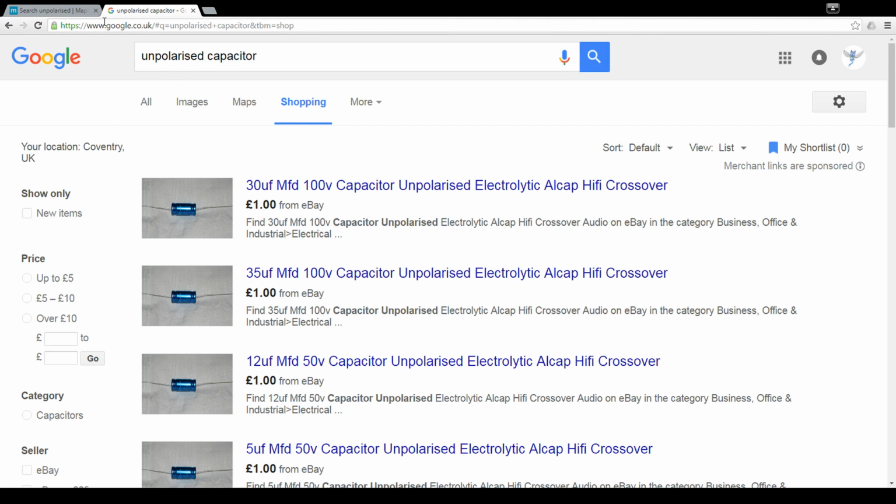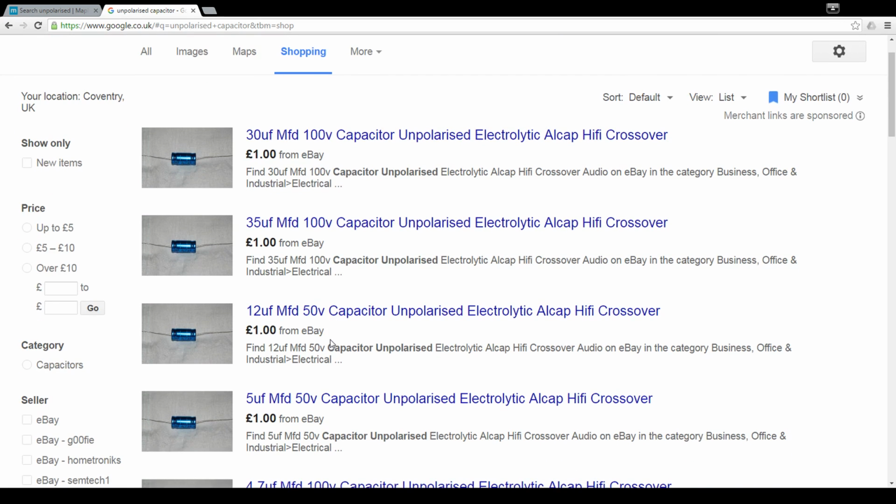As you can see, they do look like normal capacitors, but they are, in fact, unpolarized, meaning you can use them in AC circuits without them exploding like you'd expect with a normal polarized electrolytic capacitor. Where you would use the other types of capacitors, like ceramic, I think it was tantalum bead, something like that.